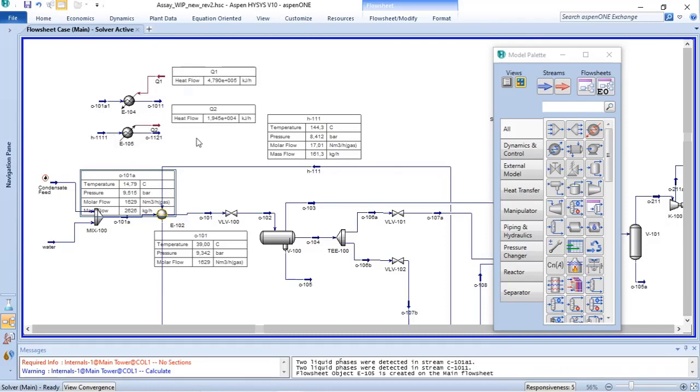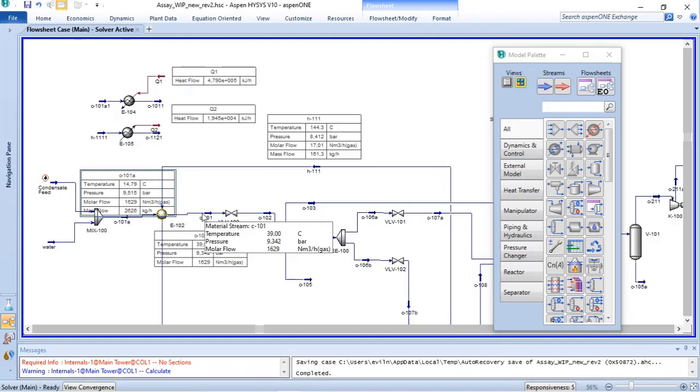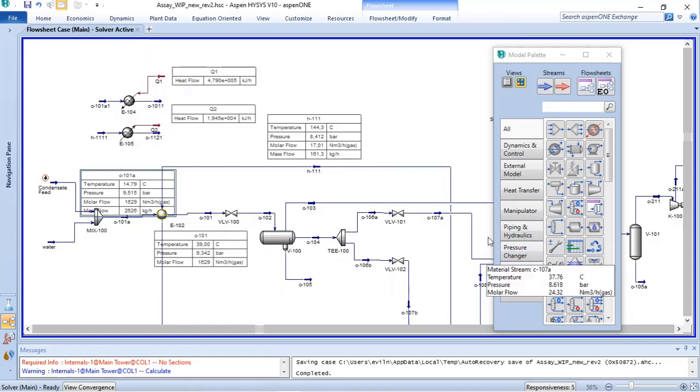But you should be asking yourself, if it's not feasible, why did Aspen HYSYS converge the simulation? It takes in consideration the overview of the process. It is because we have this stream defined. We have the inlet stream, we have the outlet stream, we have the inlet pressure, the inlet temperature and outlet temperature. We have flow, and because of that we have specified the stream to the three-phase separator and goes on.